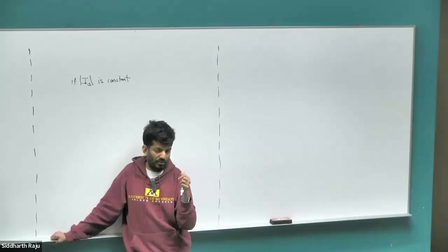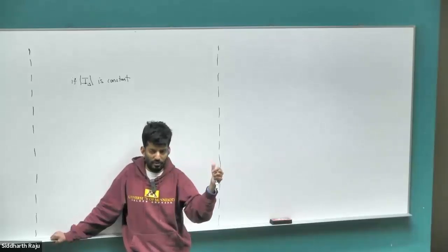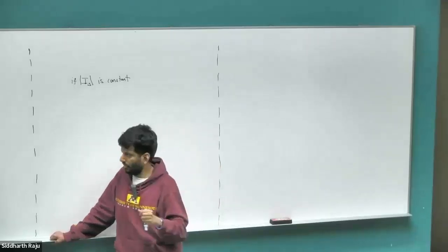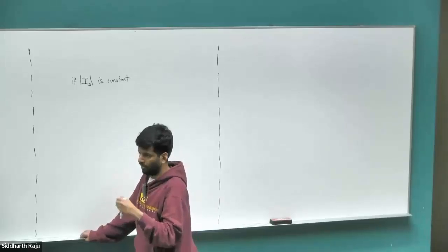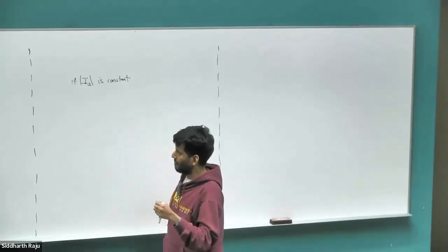And we know it's a 1:1 transformation that we have already shown before. So if you control the space vector current magnitude, then you're controlling basically the three-phase currents as well. So that's what the whole of the advanced electric drive poses, just going on to a different reference frame and simplifying a little bit more complicated problem. Right?